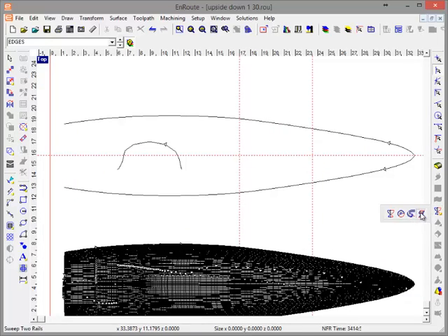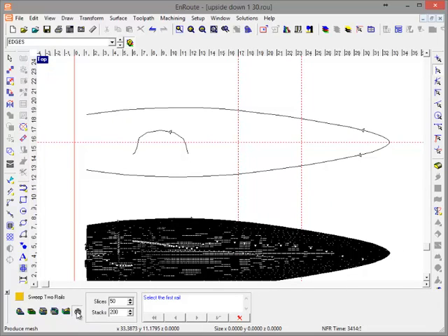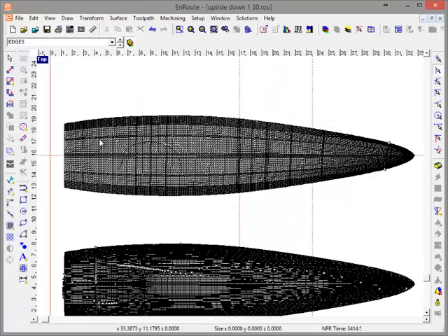So to get a mesh with sweep to rails, I'm going to hit produce mesh, which is down here. I have a few slices and stacks. Here's the first rail, here's the second rail, and here's my sweep sections, and I want to see this green line the second time I click to see that it's going all the way here. And when I hit OK, then I get a mesh object.